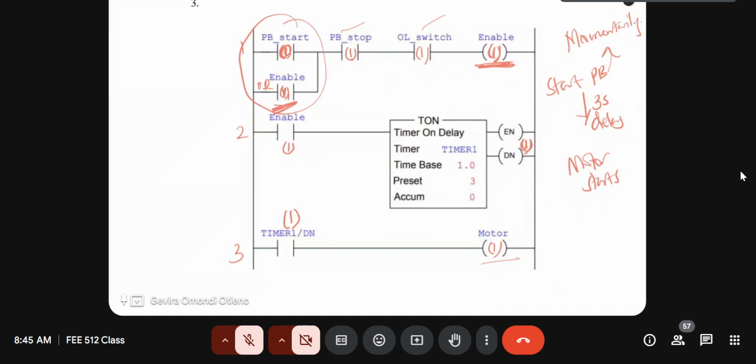The start button shouldn't really be in close proximity to the motor itself. So if there were such conditions, then I would have a switch in a safety room and the motor in its own production hall. So I'm not in any way endangered.